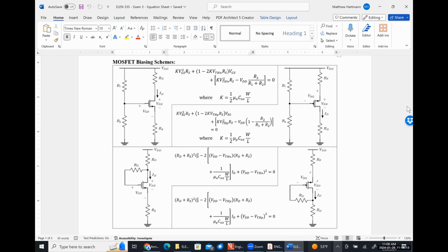Yes, with the modes of operation, I'll put that on there. I'll put everything in terms of VBE and VCE, and that's it. Meaning if VCE is greater than VBE, which is greater than 0, it's in the forward active region. If VBE is greater than VCE, which is greater than 0, that would be saturation. And then cutoff is effectively VBE less than 0. And we won't worry about reverse active because, like I said, it's never intentionally that.